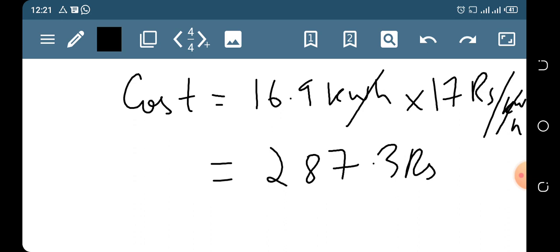Like for AC, a 1 ton AC takes around 1 kilowatt hour, one thousand watt or 1 kilowatt in 1 hour. If you run this AC 6 hours, multiply 1 kilowatt by 6, so there will be 6 units daily, and multiplying by 17 rupees, you can calculate the cost of energy for one day, which will be reflected in the month's K Electric bill.